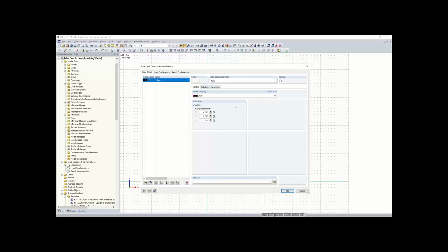And what this means is for this load case, a -1 factor is going to be applied to the self-weight of the structure. And that's just going to take into consideration that force that's being applied to your structure. So if you have multiple load cases, you only need to keep self-weight activated for your dead load case, and that will take into consideration your whole structure. So perfect. Thank you. You're welcome.